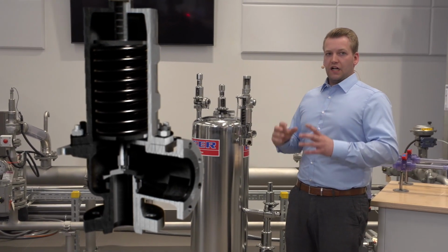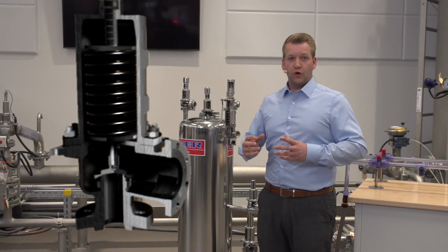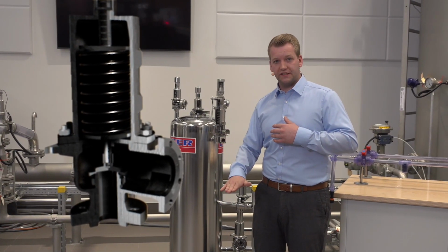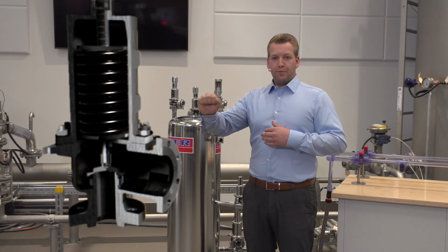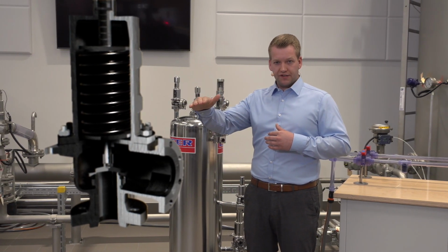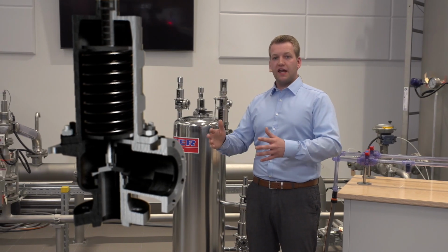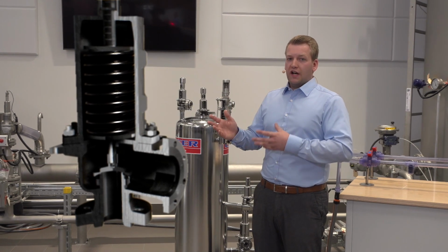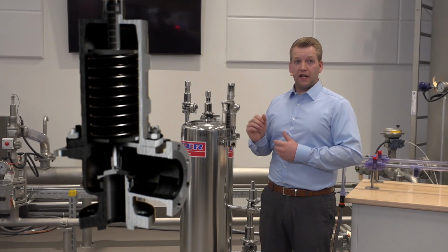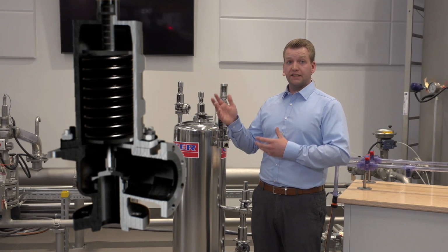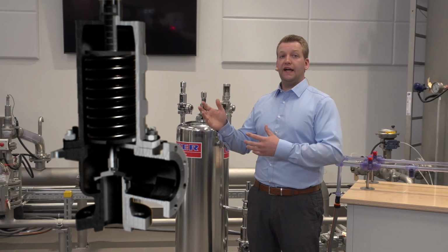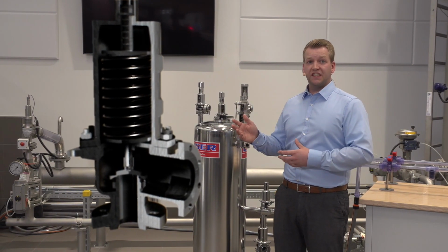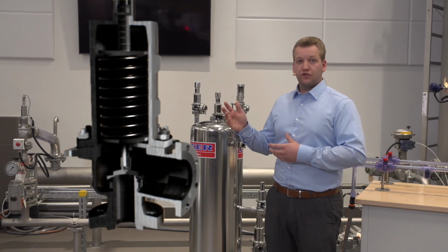So this is the dead space ratio. I'll explain it again. It is the length from the protected system to the safety valve disc in relation to the inlet diameter of this safety valve. And the problem in a cleaning process with a standard safety valve is that we have a high dead space ratio, here roughly 6.